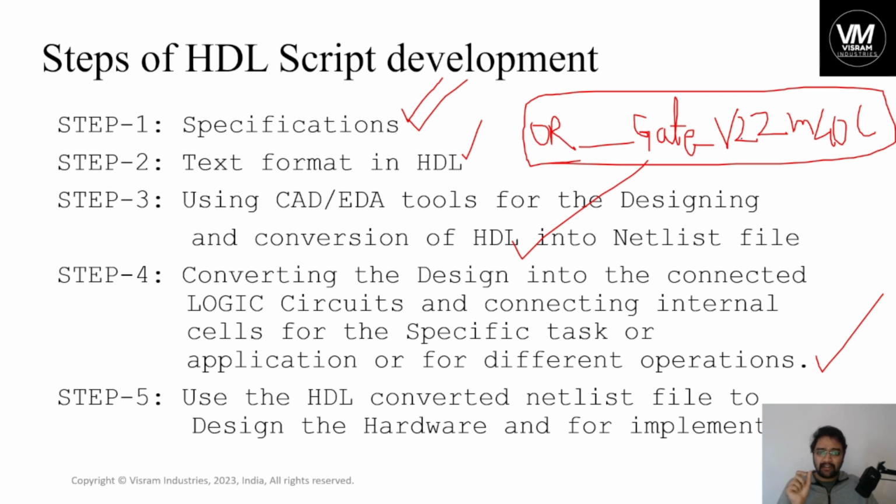That OR gate technology will be abstracted from the existing libraries. There might be many OR gates with 3.3 volts, and some use 5 volts if they are operating a larger data bus. So depending on the OR gate that you require and as per the HDL that you specify, you will get the OR gate from the libraries, and that library cell is attached to your hardware description.